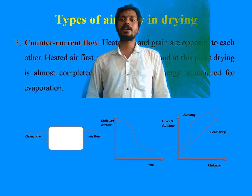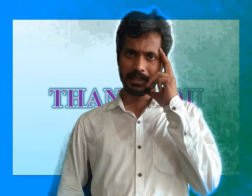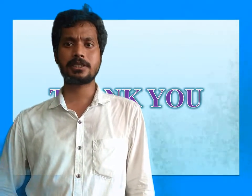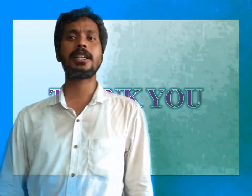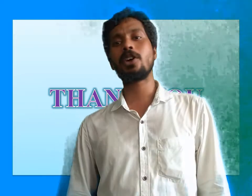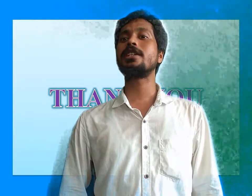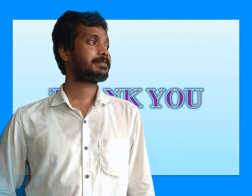So now here I would like to finish today's lecture. Before I finish this class, I'd like to revise the topics which we discussed today. So today we discussed unsteady state drying. In unsteady state drying, we have seen the moisture ratio. Moisture ratio is M minus Me by M naught minus Me, where M is final moisture, Me is equilibrium moisture, M naught is initial moisture, and all the moisture contents are in decimal and dry basis.